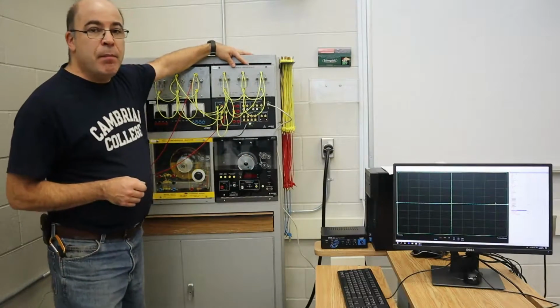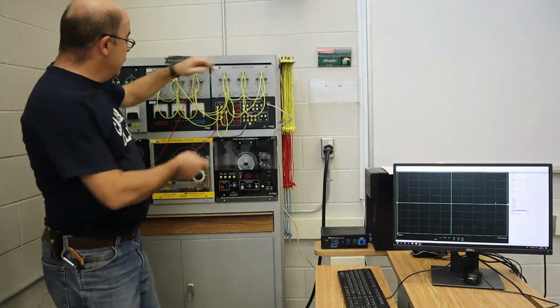What I'm going to do is show you, my viewer, how the voltage and current waveforms react at different points of a circuit. According to the popular theory, when we have a resistive component in a circuit, the voltage and current are in phase with one another. Over here, the inductive load module: according to the popular theory, inductors oppose a change of current, and that is going to create a 90-degree phase angle difference between the voltage and the current waveform.